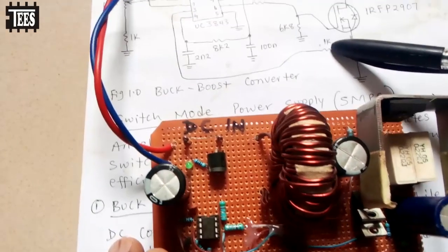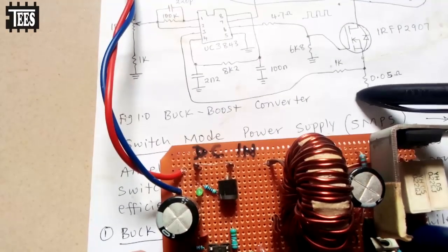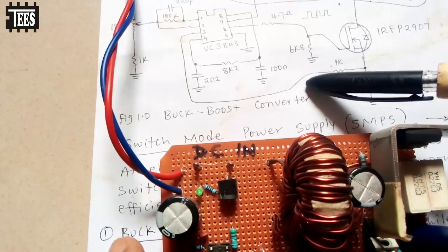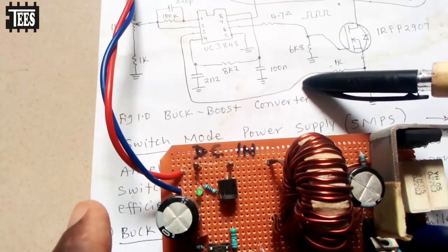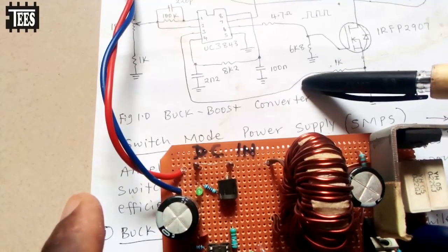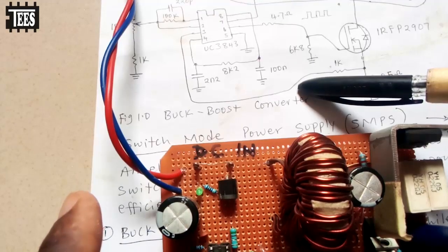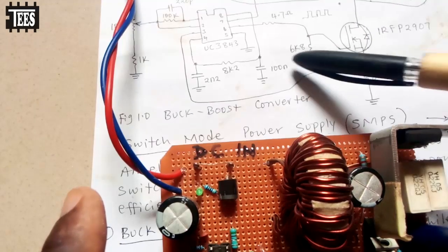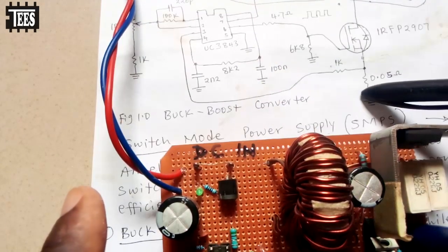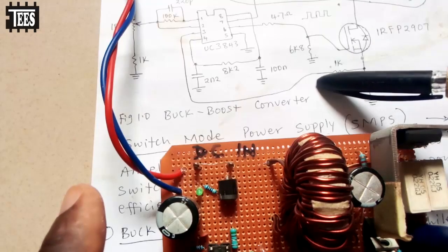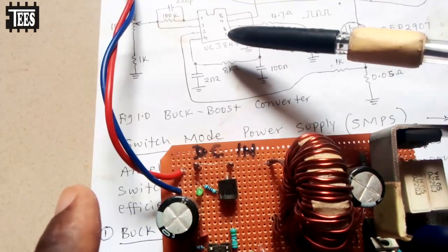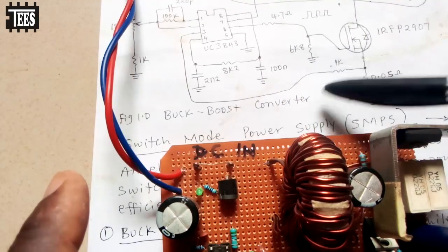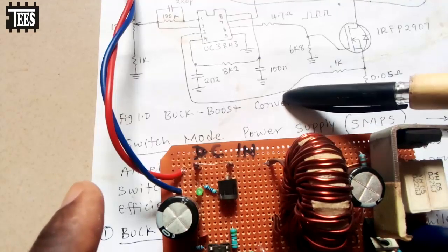Now, why is this resistor there? In case something bad happens here. If I were designing this again, I would put a Zener diode here, for example a 5 volt Zener diode, so that in case something happens here, you don't blow this IC. Because if this place is disconnected, the whole voltage that's supposed to go to ground will try to pass through the IC to ground, and you can blow this IC up. So make sure the resistor is there first before you put your Zener diode, although I didn't put the Zener diode.